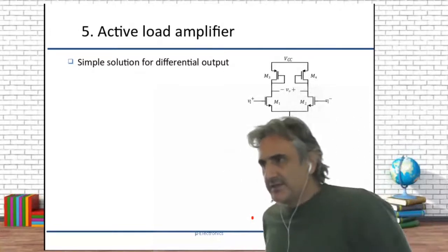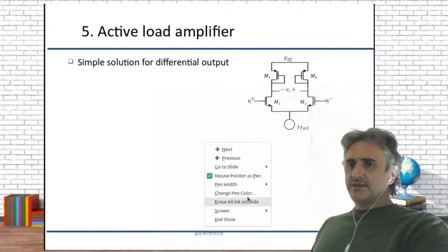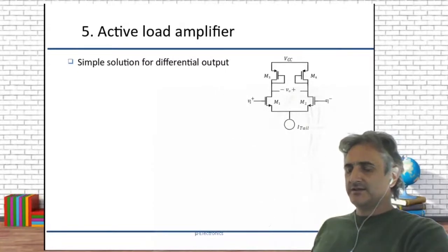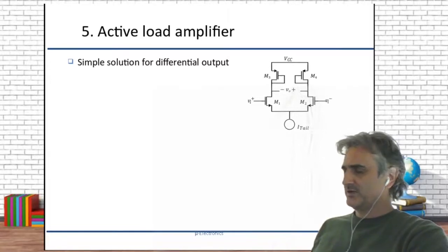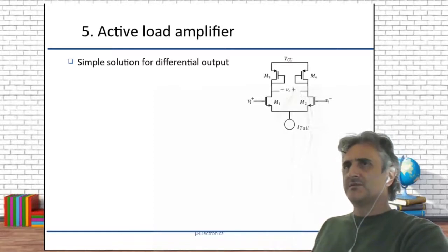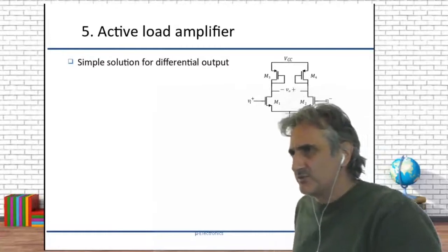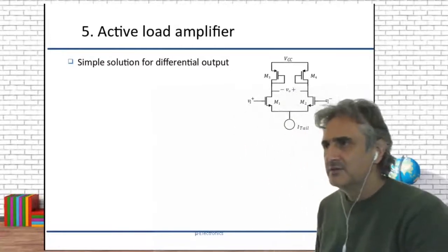Then the problem is, how can we integrate this in an integrated circuit, is that it's very complex to integrate resistors. They are awfully difficult to implement, and the values are always very complex to get.